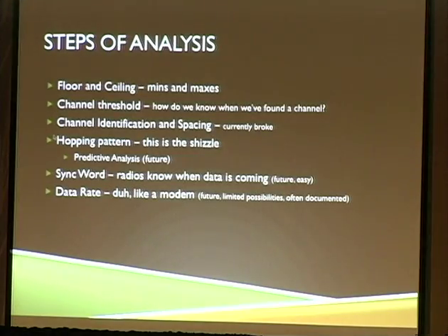So, frequency hopping analysis. The way to break frequency hopping is determine, first of all, your floor and ceiling, and pick a threshold that determines a channel, and then determine your channel spacing. Then determine your hopping pattern. This is actually not that simple. And our code is actually very rudimentary right now for what we have planned.